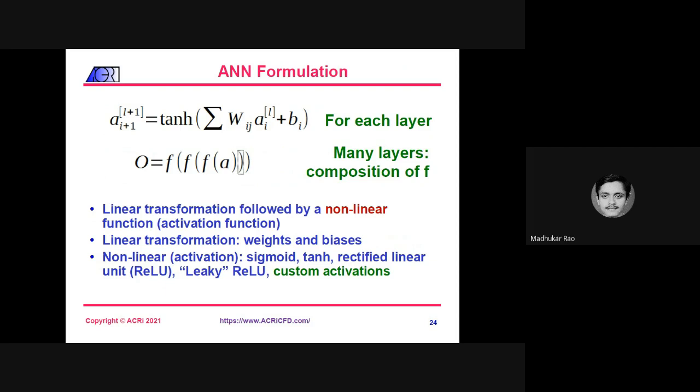Just keep in mind that the rectified linear unit and the leaky ReLUs are not infinitely differentiable. So normally I do not use them when trying to fit CFD results, because after one differentiation, they become constant. The second derivative is 0, so I cannot represent my viscous terms. So I don't use those two activations.